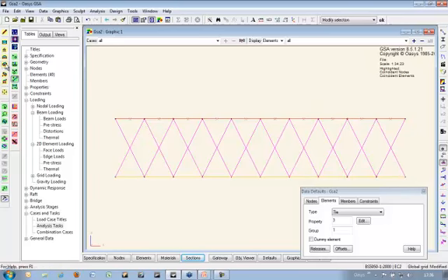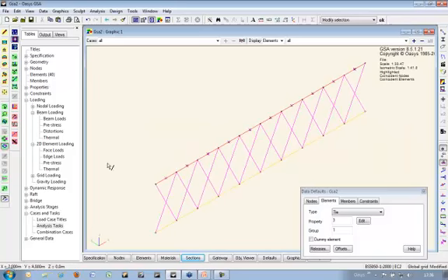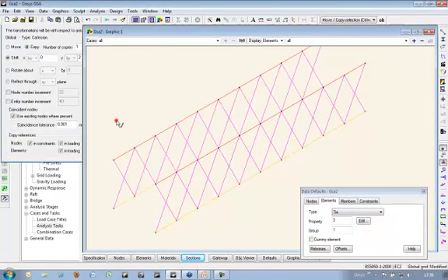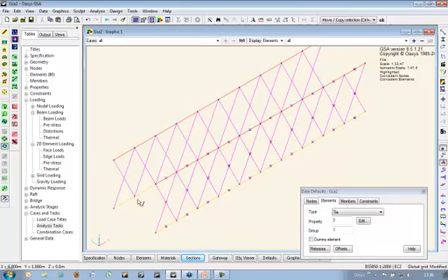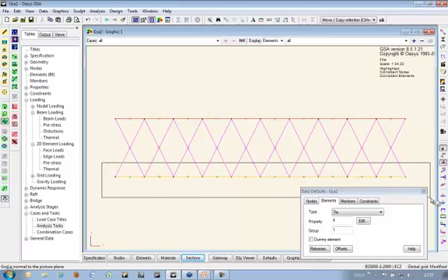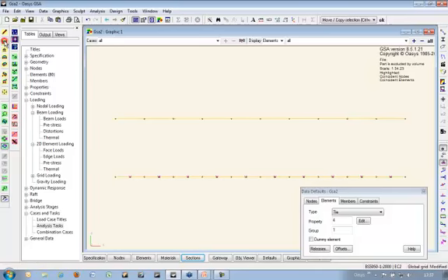Okay, and let's copy all of those 2 meters in the Y direction, and then I'll zigzag at the bottom, which I'll set to property number 4. And so I can see it easier, I will use a volume and just draw them in here.